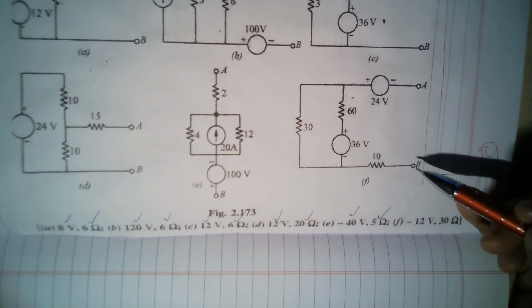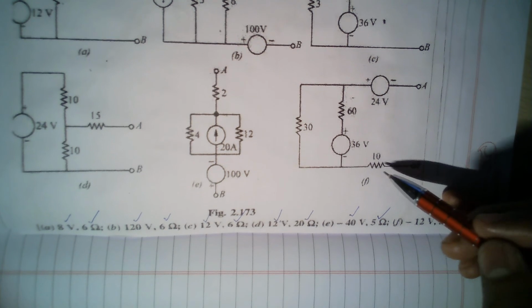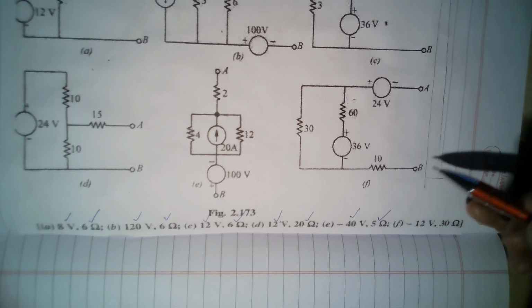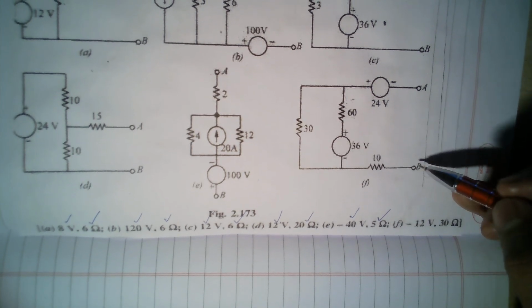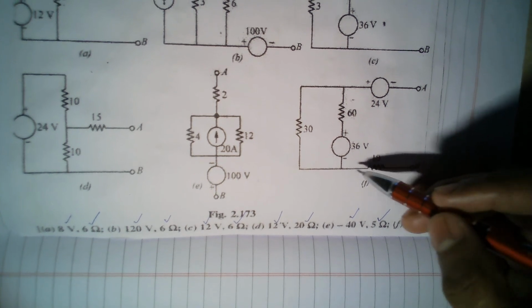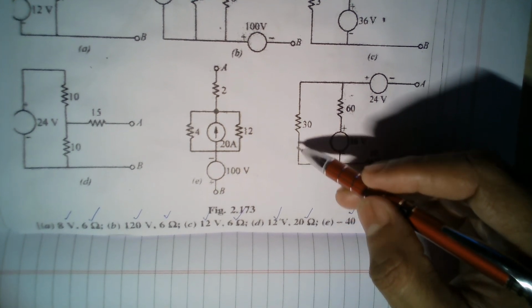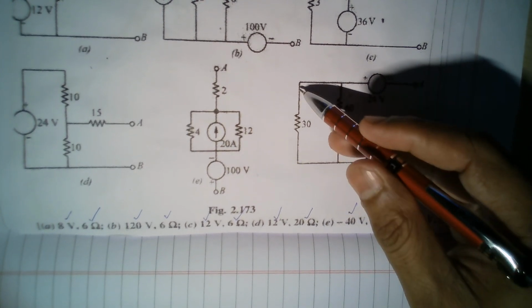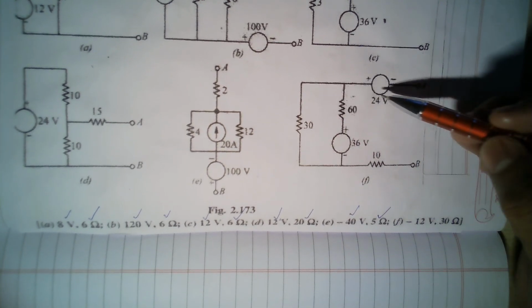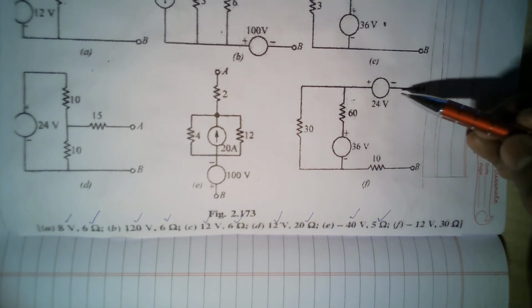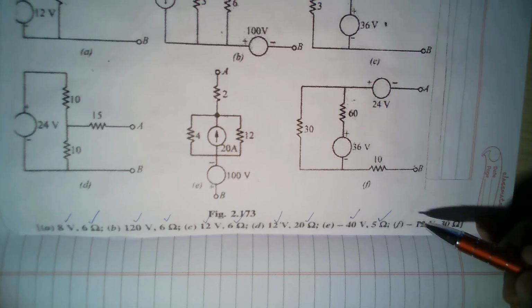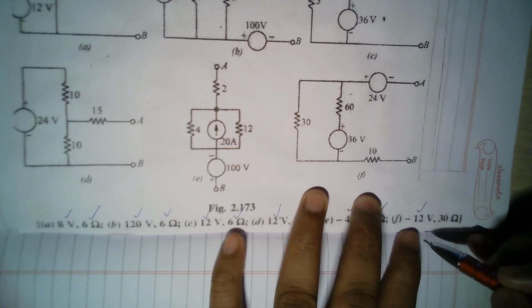So now I start the Kirchhoff voltage law from B, 0. By the way, impedance I did not calculate. Anyway, directly I am calculating the Thevenin's voltage. So from B, nothing, no drop here. And here it is 12 volts I calculated. So from here to here if I go, I gain 12 volts, so plus 12. And from here, plus towards minus I lose 12 volts. So finally by the time I go from B to A, I have achieved minus 12 volts. So that is the Thevenin's voltage.